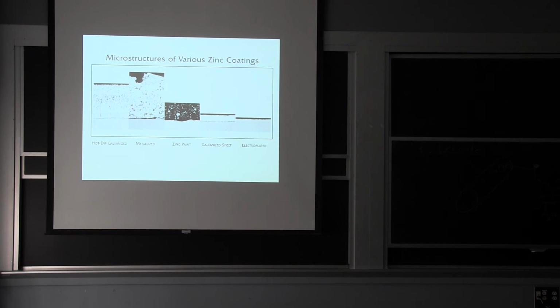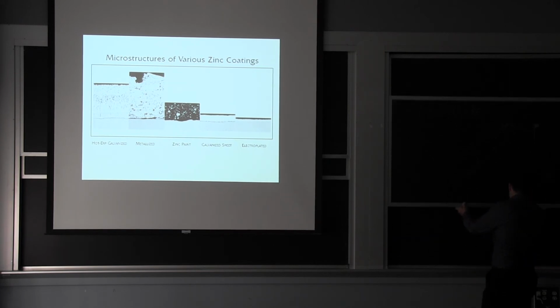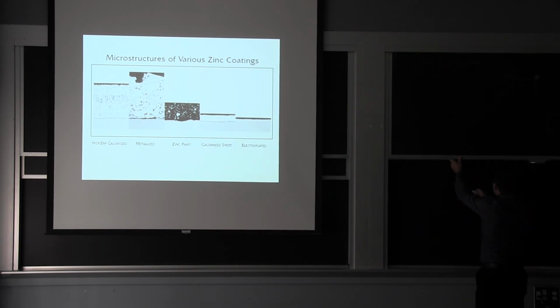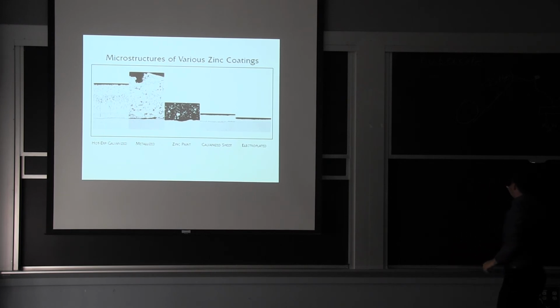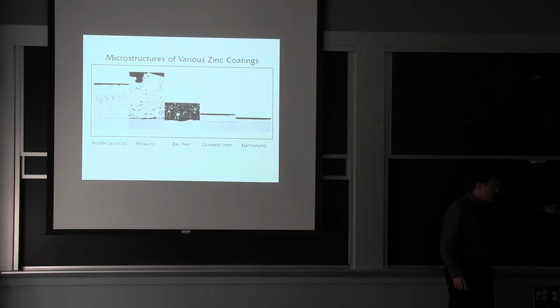And with hot dip galvanizing, you're talking about 2 mils thickness as typical. You can go to 5, so I'm just going to put a range. But it's fairly thick. So 2 mils is 1/20 of a millimeter. So it starts at 200 micrometers going up to 500. Yeah, I think. No, I'm screwing up here. Anyway, these numbers I know, and then you have to translate it back.